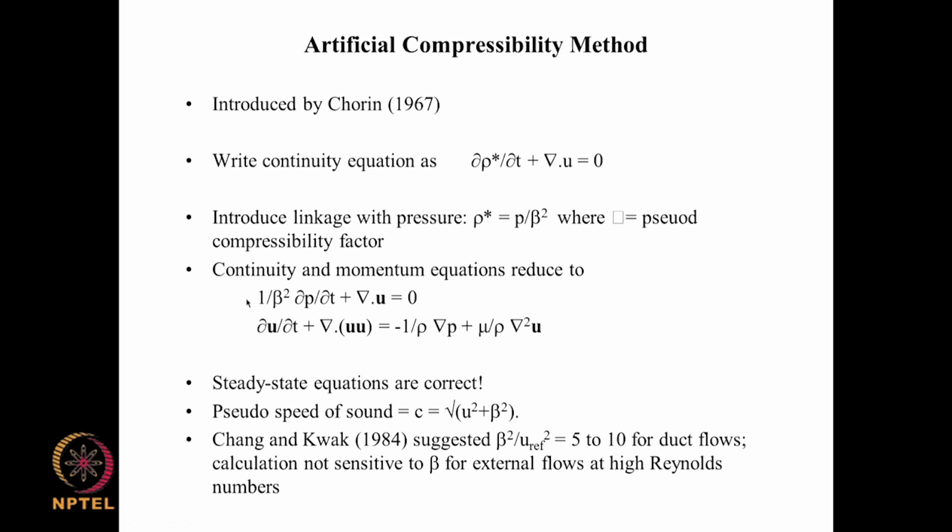By rewriting the equations this way, through the addition of this artificial compressibility term, we create a method of finding P and putting it in the momentum equations, so that it is no longer a nuisance variable but a known variable, and it varies from point to point because it is given by this equation. So pressure is a function of x, y, z, t, and that same variation is put here to get u. These equations can be solved using the methods that we discussed in the previous part of module 4, which enables us to extend those methods here.